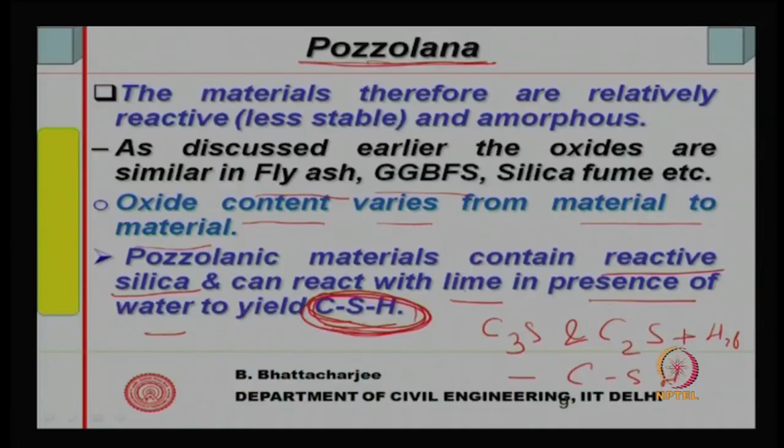Okay. So this reaction of lime with silica in the presence of water is called the pozzolanic reaction. The materials which exhibit pozzolanic reaction we call pozzolana. Most of the mineral admixtures which you use in concrete are basically pozzolanic in nature.